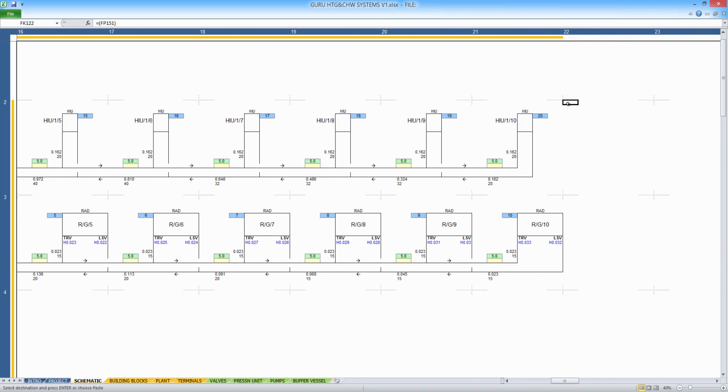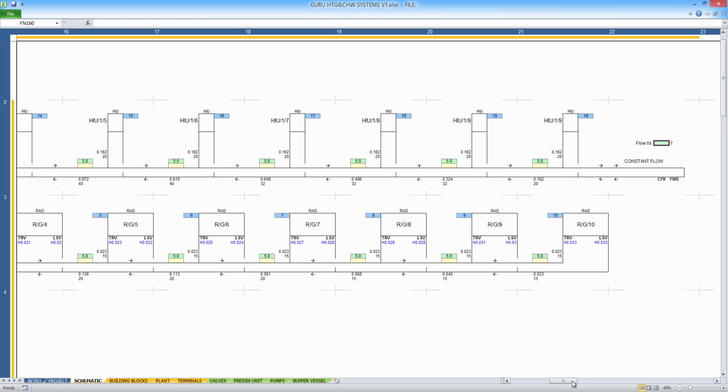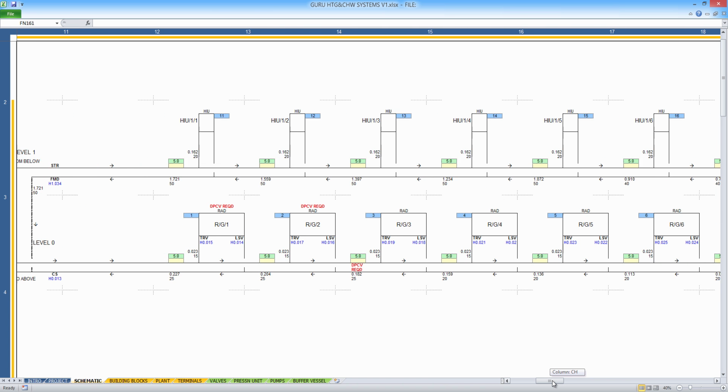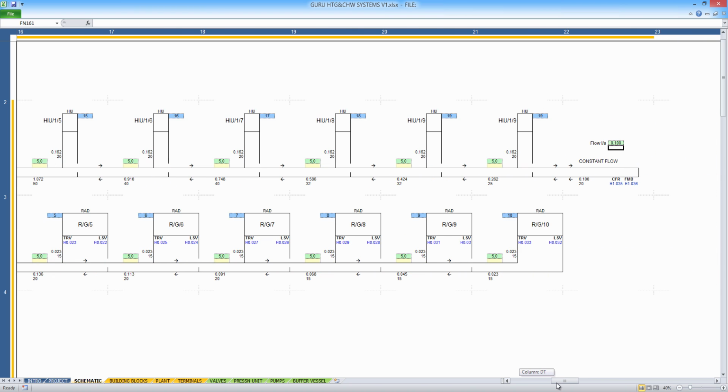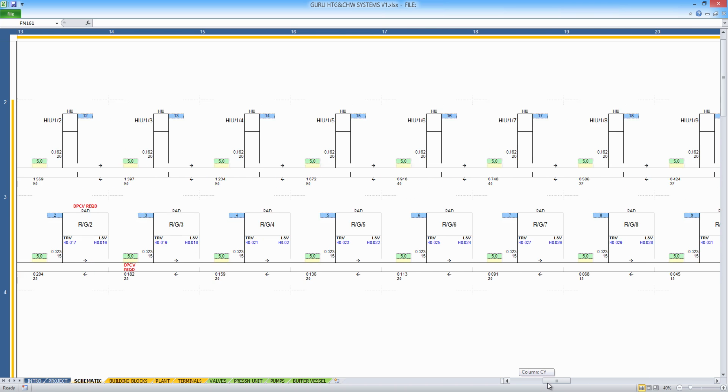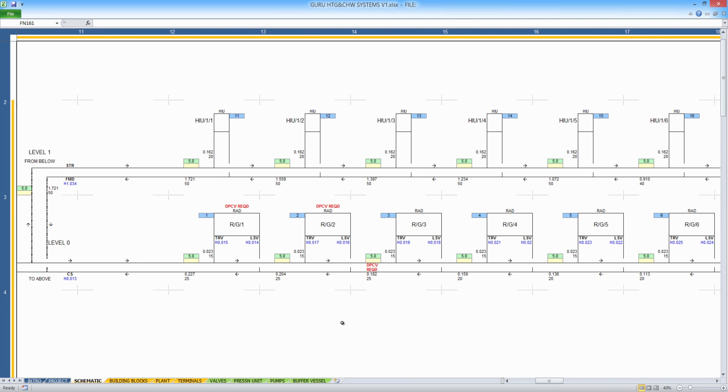I can put one on the end of this run, and if I copy one of those into the end space, that'll connect it up. I need to give it a value. Ideally you need to aim for between 5 and 10%. I think that's equivalent to about 0.1 litres per second in this particular system, and indeed that's enough to clear the warning. So that's that warning dealt with. I now have a permanent bypass there, which allows the pump always to have somewhere to pump.